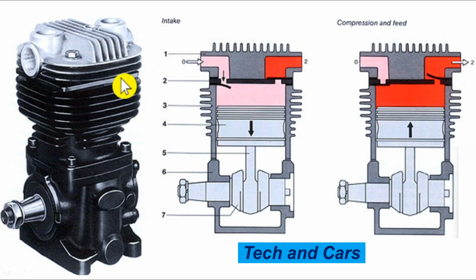And in some cases, you should allow the compressor to cycle properly as well. The compressor needs to reach its full operating temperature to boil off any internal moisture that is trapped in here. In order to do that, the compressor should be run for a longer period so that it will have enough temperature to burn off and evaporate any moisture that is trapped in here. However, if you are primarily making short trips, you should periodically take longer trips to allow the air compressor to reach its operating temperature so that it can fully evaporate any trapped moisture in the system.